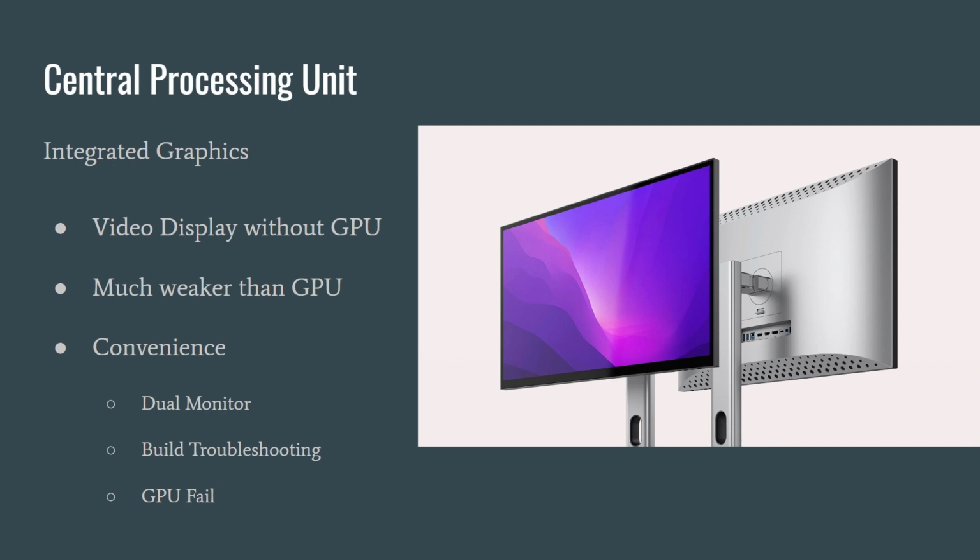And then you can also do things like build troubleshooting. So say you're worried that you have an incompatible GPU while you're building your computer. Well, you have no way to know what part is bringing your computer down because you can't even get a display. You can't even see the BIOS because there's nothing to show the graphics for your display.